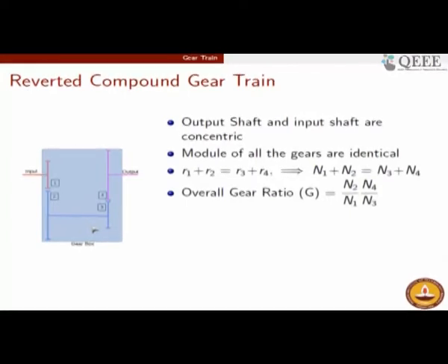This blue box is the gearbox, and all the gears will be packed inside it. So obviously you want to make this gearbox size minimal, and you can work this out as part of an optimization exercise. It so happens that the gearbox size will be minimal if the gear ratio in both the stages is equal. We know the ratio for one stage is, let's say, G1 and the other stage is G2. If you choose G1 and G2 to be different, then the overall size of the gearbox is going to be bigger, because you are going to need one big gear to accommodate their unequalness in the gear ratios. Rather, it is better to choose the gear ratios in both the stages to be the same.